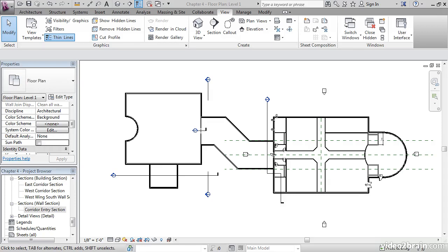In this lesson, we're going to create some callouts. Yes, callouts are still just another type of view. In fact, they are very similar to a section. What a callout does is take an area of a view and create a new view by enlarging the scale of the area. Just like a detail, callouts are dynamically linked to the original plan or section in which it was created. The objective of this exercise is to create a callout for a section in the lavatories.